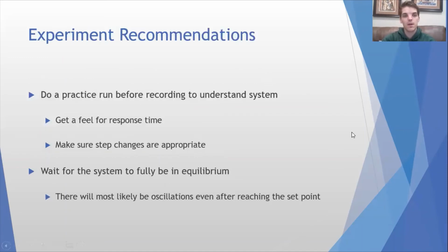Next, I'll talk a little bit about the experiment recommendations overall, just so you guys don't pull your hair out while you're in the lab or get stuck in the lab for 3 hours or have to go back. Do a practice run before you're actually doing your experiment and recording stuff. This is going to help you. It just gives you a feel for the response time of the system of that day, and it helps to make sure that your step changes are reasonable.